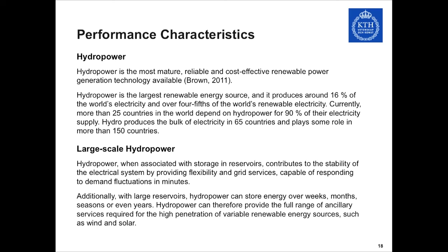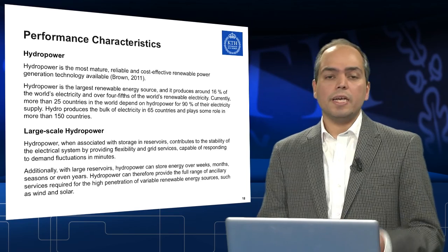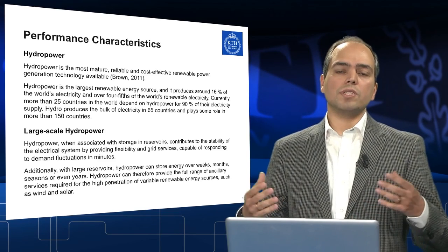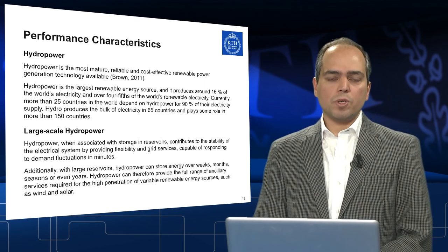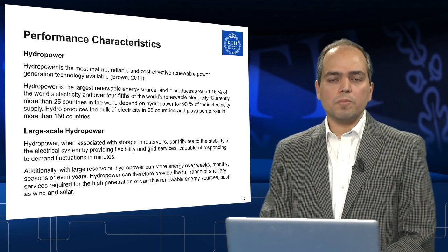When it comes to large-scale hydropower plants, they are associated with the storage of water in reservoirs. And this contributes to the stability of the electrical system, because these systems are connected to the grid, and they provide the flexibility which is needed in an electricity network. And large hydropower plants can in fact store energy over weeks or even over a season, depending on the availability of water. So the flexibility of the large-scale hydropower scheme is very important.